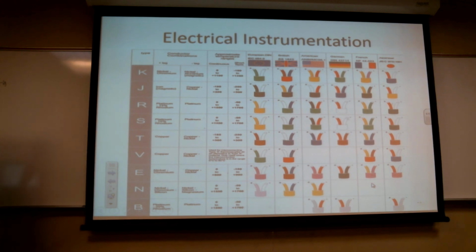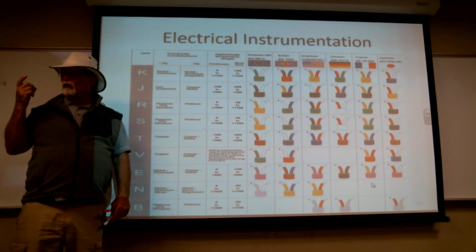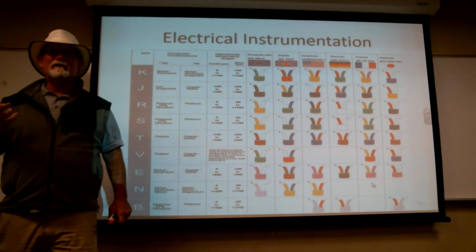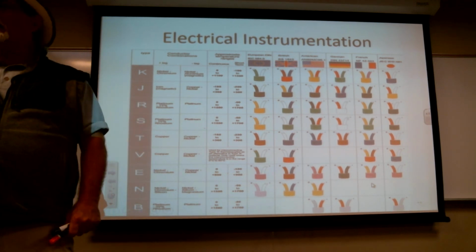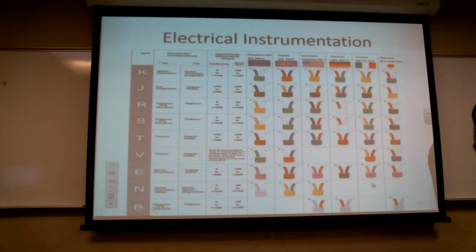In fact, exclusively. CHT and EGTs, the package, the probe, the way the probe is configured, the way it's mounted in, there'll be a bunch of different ways of doing that. Fairly commonly, the manufacturer, like Lycoming and Continental, they have a little threaded port in the head that's just a dead-end port that you screw a little plug in, and then the temperature probe is encased, the cold or hot junction is encased in a little stainless steel adapter with a little quarter turn like a BNC connector.